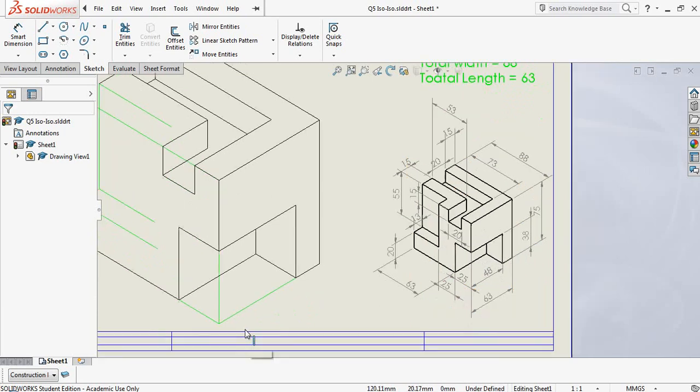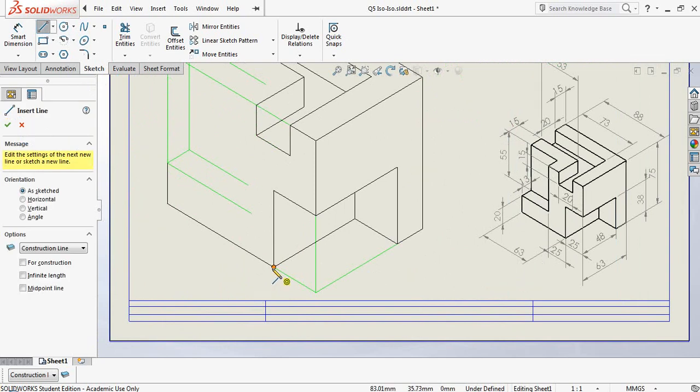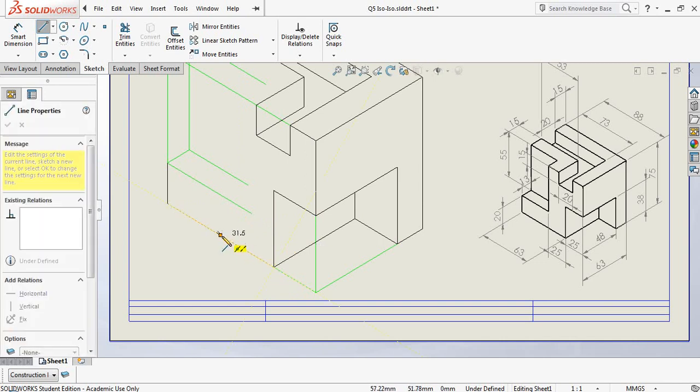That's interesting. So we're using some deduction theory over here, and I'm going to be measuring a line length from here to this side over here, 25 millimeters apart. So I'm going to go along my 30 degree line, my isometric line, and I'm going to find a line length of 25.